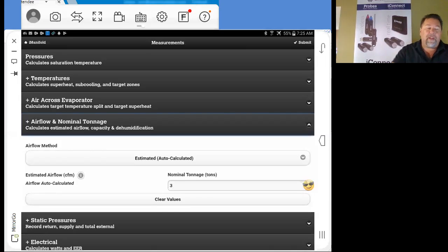Now you can put in capacities on the equipment information. Now that's another module that we're going to go into with advanced reporting utilizing cloud, and that will go into utilizing the AHRI database with cloud, because that will actually enter in the capacities of the system from the AHRI database. So you have a 3-ton nominal system. When they're tested out with AHRI, they're actually 31,400 BTUs. So you're comparing apples to apples. Everything will be put in there and the actual capacity measurements from AHRI.